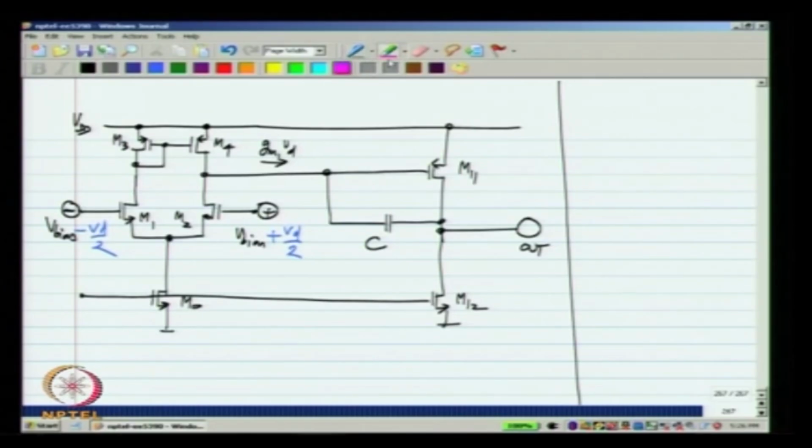So, first of all, what is C1? C1 is the total capacitance at the output of the first stage, and that consists of parasitic capacitances from every transistor that is connected there, M4, M2 and M11. As usual, I will neglect the values of CGDs because the transistors are operating in saturation region. So, C1 will be CDB4 plus CDB2 plus CGS11. So, that is what we have, this one, that one and that one. Remember, VDD is small signal ground.